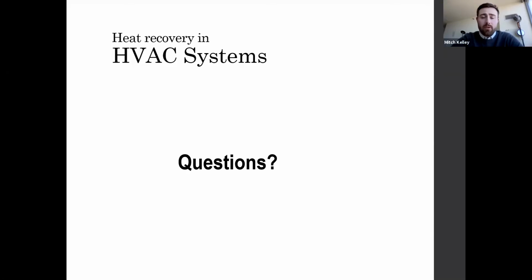Now, if we're talking about a net zero facility and we just need that temperature of water and we can't use fossil fuels, that may be justified. But in many cases, if we're just looking at a simple cost balance between burning fossil fuels to create hot water and using a chiller to do so, it's not going to be cost advantageous to create 150-plus degree water with a chiller, although it can be done.